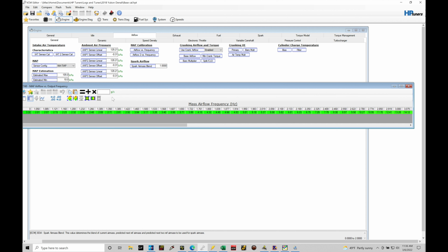Now, the mass airflow sensor is really only valid in steady state conditions. We can't have rapid throttle changes and bursts of airflow entering our engine. If we have a transient condition, say going from off throttle to slamming the throttle all the way open, we have a huge burst of airflow, and the mass airflow reading isn't going to be super accurate in terms of air mass. In steady state conditions, the mass airflow sensors are incredibly accurate.